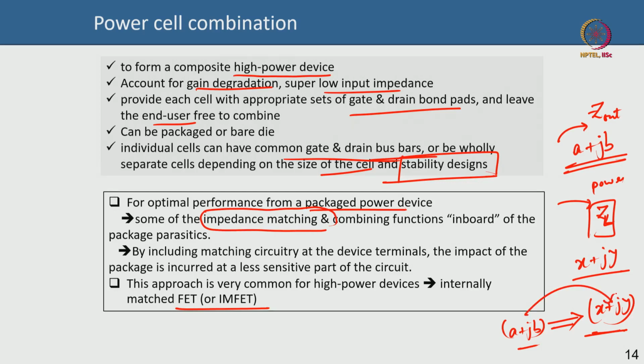It is called impedance matching. Only then your reflection will be minimum. Semi-qualitatively speaking, what it means is that your RF signal that propagates, and there is a load here, ZL, it will hit the load and it will bounce back and return, correct. So that reflection, you want that reflection to be minimal, as close to possible 0, so that whatever you are sending should transmit, it should not reflect and come back to the device again.